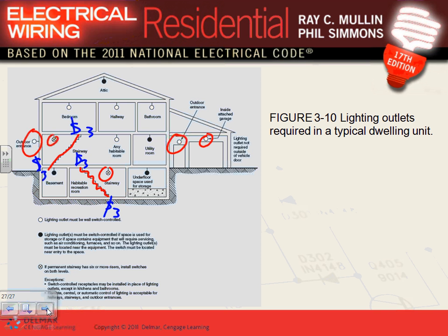Yes, sir. So let's say, in a family room, where you have to have at least one light switch, can you use a split receptacle? Yes. In habitable areas, you can use a switched receptacle as that light. Except this is not approved in 4 locations. You can't use a receptacle there.